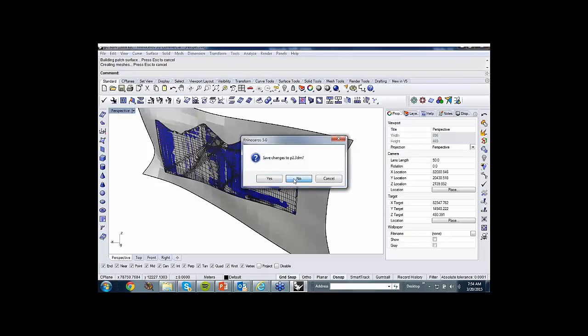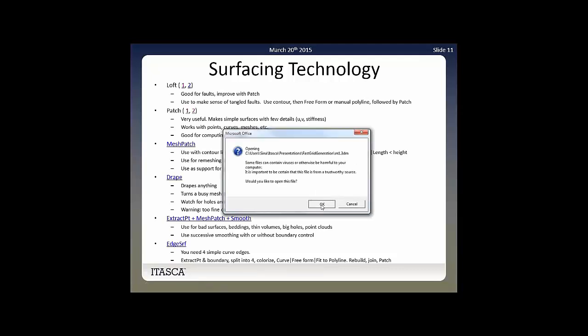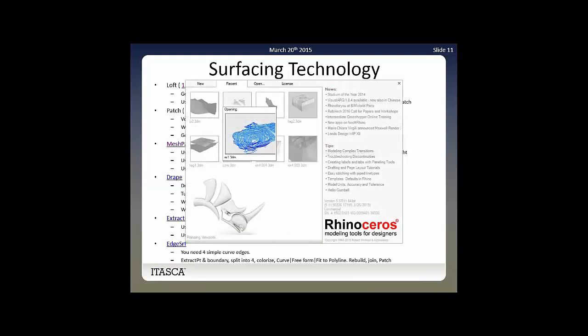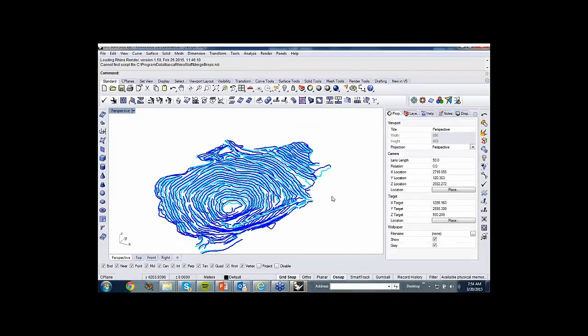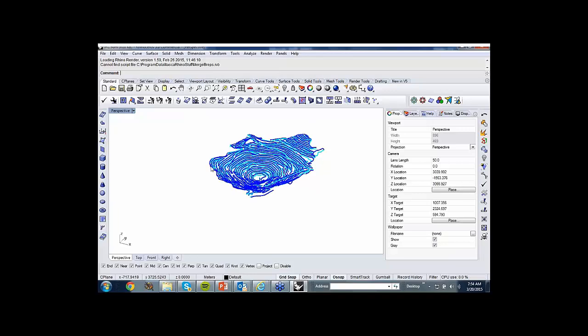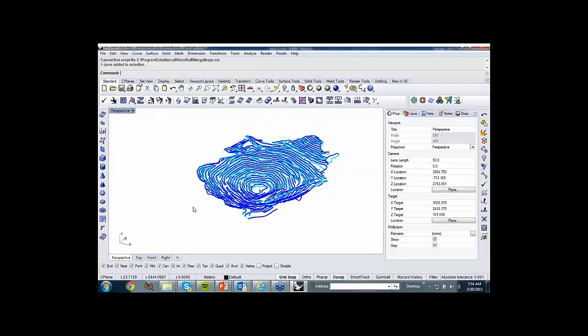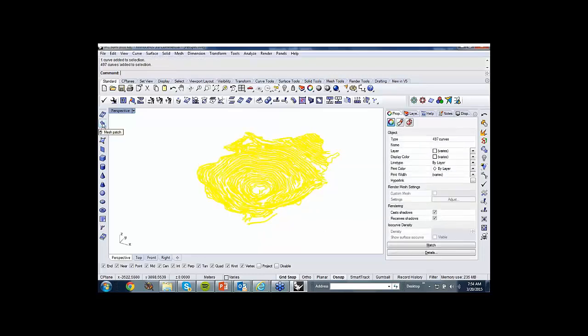I'm going to move now to mesh patch. Mesh patch, you're familiar with that. This produces a mesh, so it's coming up here. One thing that I really would like to point out with regard to this mesh patch is, the idea is that you have a collection of these polylines or curves, and you say, pass a mesh through that. If I select these things and type this command, mesh patch, it will try to extract points automatically from these curves, and sometimes it will take a long time. It will produce a mesh, but it's not good enough.